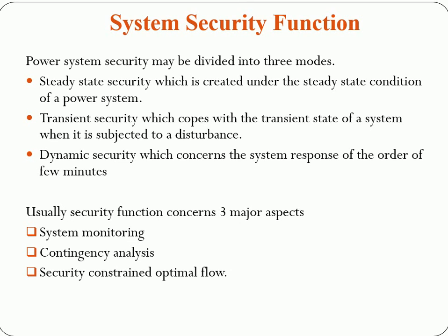The function of contingency analysis is aimed at dealing with problems that happen within a short duration, since they occur so quickly that no operator could take action in time. This is often how cascading failure comes out. In order to refrain from this, we need to implement the contingency analysis program into our operation computer to eliminate the troubles before they arise as much as possible.